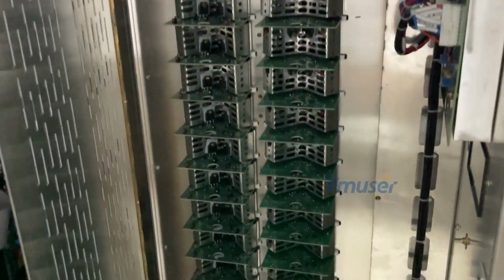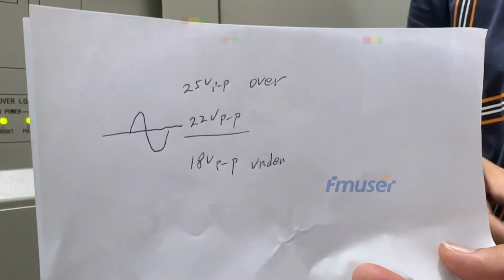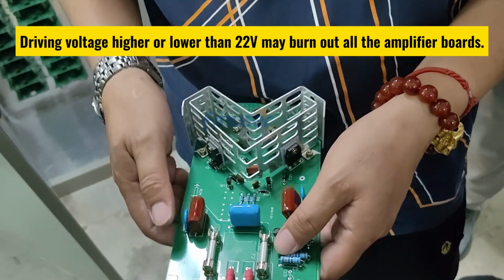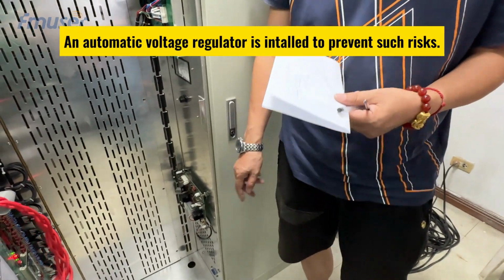In the case of a 10 kW AM transmitter equipped with 48 small power amplifier boards, it is crucial to maintain the driving voltage at the standard level of 22 volts. Deviation from this standard voltage, either higher or lower, can lead to extensive burnout across all power amplifier boards. To mitigate such risks, an automatic voltage regulator is installed. Once the driving voltage falls below or exceeds the normal ground state, the regulator actively prevents adjustment, triggering an automatic shutdown to safeguard the power amplifier boards.